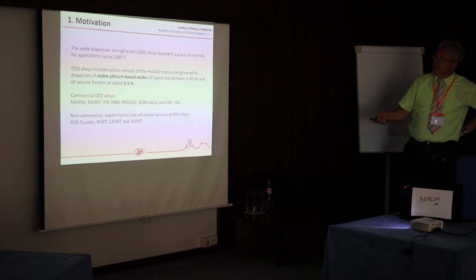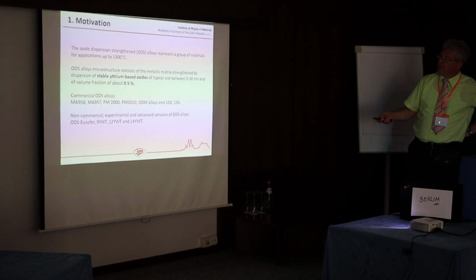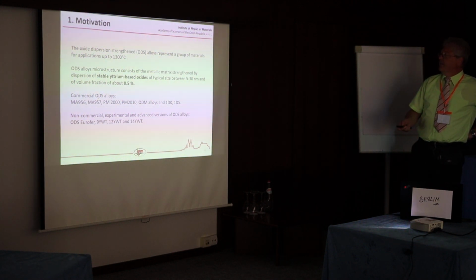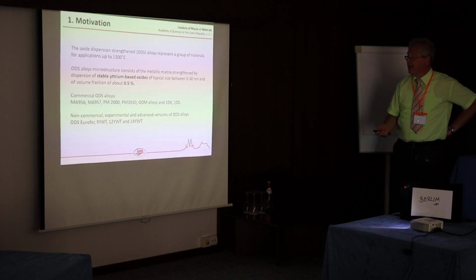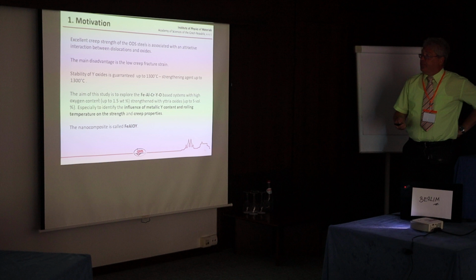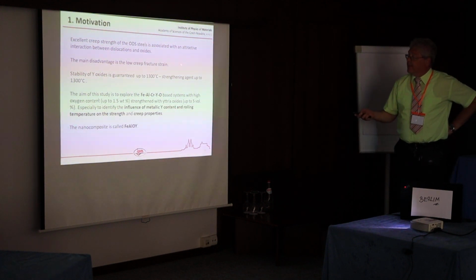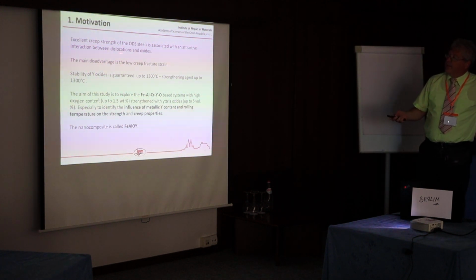So currently the use of yttrium oxide is about 0.5% of volumic fraction in the materials. There are some commercially produced or non-commercially produced materials, and they have very good creep strength due to interaction between the dislocations and oxides.